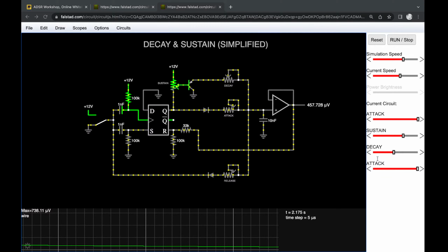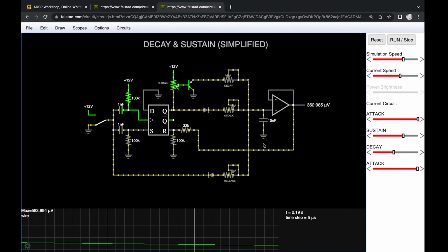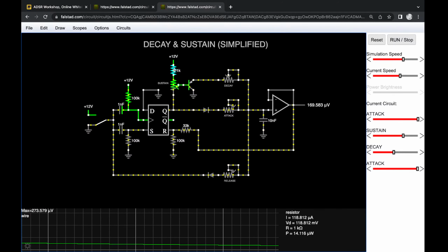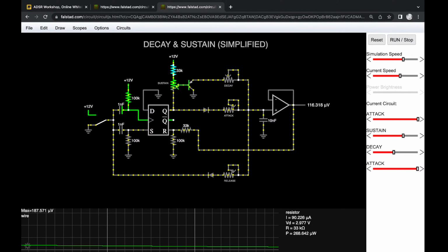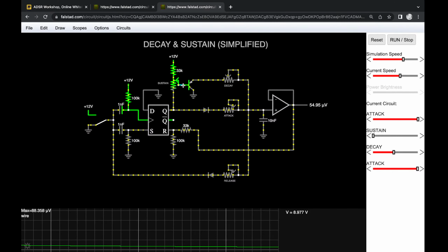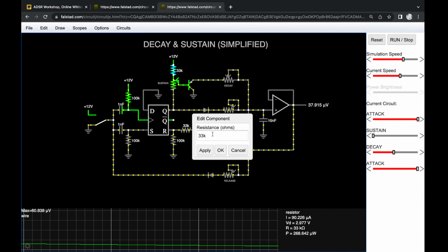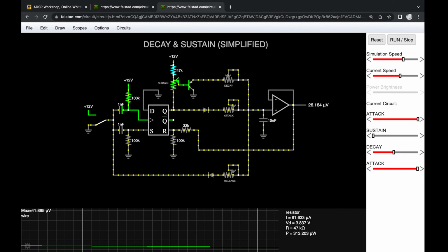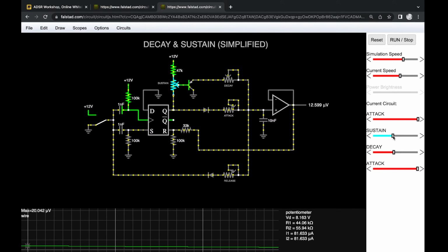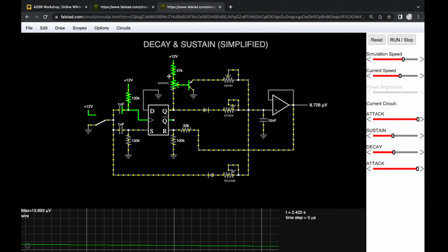And then Dabroni says, why can't you use a voltage divider before the sustain port? That might actually work, right? We could maybe just put a resistor here, I guess. If we put one here and give it like 33K, then I'm guessing the highest voltage will be, now it's 9. So we need to give it a little bit more. Let's try with a 47K. Right, now it's 8. Perfect. Yeah, good suggestion. It's not a voltage divider, a resistor is enough, right?